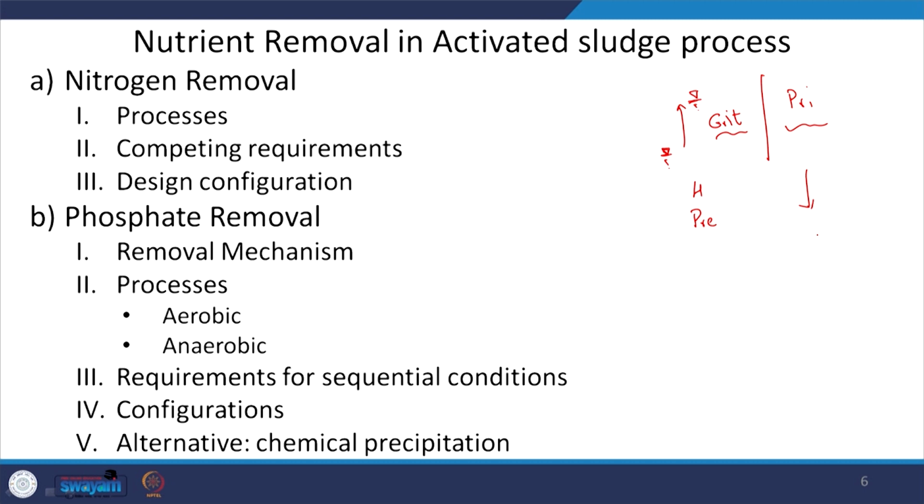So, that is up to the relevant plant designer or such. Primary treatment, what am I trying to remove here? Primarily those compounds that are suspended in the water or wastewater, but which are heavy enough to be removed within a reasonable amount of time. So, mostly suspended matter and some BOD also, I think we mentioned around 30%.